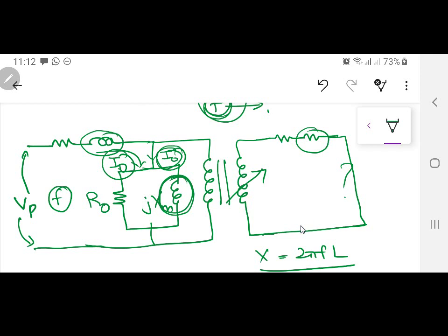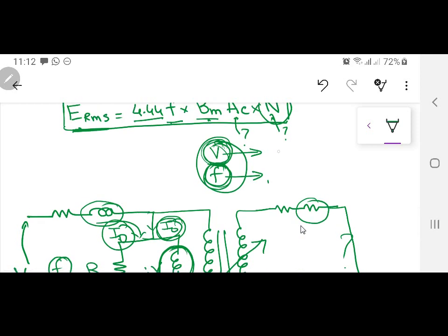So if you want the same value of torque, at least at that value, then you have to have V/F ratio constant. हाँ, इंडक्शन मशीन के अंदर if you are increasing V, this will not work, मशीन डैमेज हो जाएगी, because again insulation is not going to work over there. फ्रीक्वेंसी आप बढ़ा सकते हैं, वोल्टेज नहीं बढ़ा सकते. फ्रीक्वेंसी बढ़ाने का हमें फायदा क्या था इंडक्शन मशीन में? स्पीड इंक्रीज हो रही थी, लेकिन वोल्टेज वही के वही रहेंगे, तो V/F रेशियो कम होगा, फ्लक्स कम होगा. जब फ्लक्स कम होगा तो टॉर्क कम हो जाएगा.